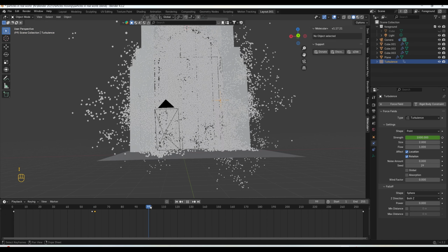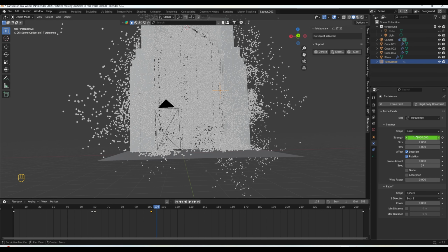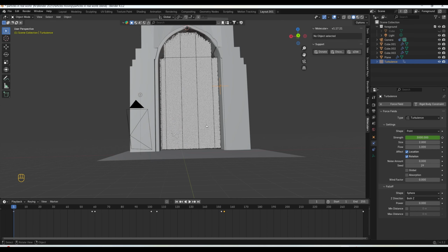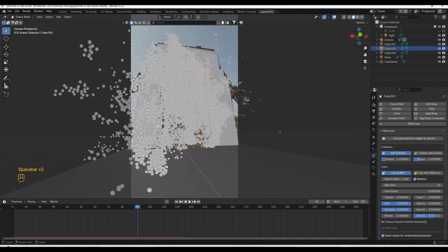I, and let's suppose after 100 I will just press one more key, and then I will just make it like 500 and just add a keyframe. Go to 150, add a keyframe, and just make it 100. So gradually I am just bringing it down, and Control S to save. Let's select this and simulate this, and let's see. So this is nice. We have a lot of particles, but these are moving very fast.